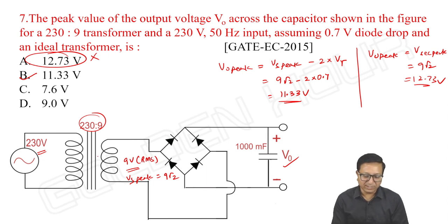It is not given like that. If the turns ratio is given as 2 or 3, that is, if the primary to secondary winding turns ratio is less, then that is a different story, but here it is more. So you can't take the ideal case. You should take V gamma into consideration. That is a bridge type rectifier, 2 diodes. The diode drop is a really appreciable value.